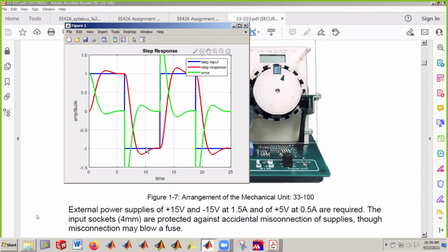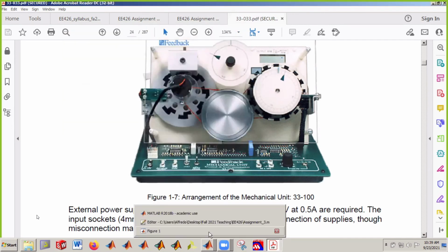Or if you are unsure what to call this, undershoot or overshoot, you can just call it a deviation, all right? Or a non-zero difference between the two, which is why we introduced the error signal. So if you're not sure how to describe this in terms of overshoot or undershoot, you can just say a significant difference in the voltages, in the magnitudes of the signal, and these are reflected by the non-zero value in the error signal. So because this is spinning the other way, in the minus direction, this would be considered overshoot, right? So you can call that overshoot.